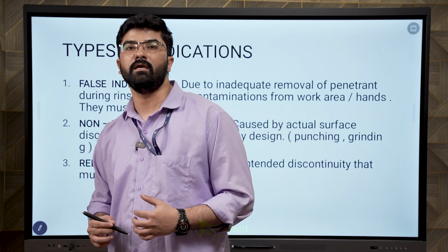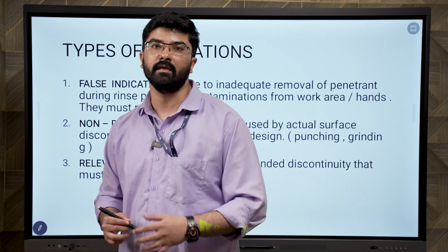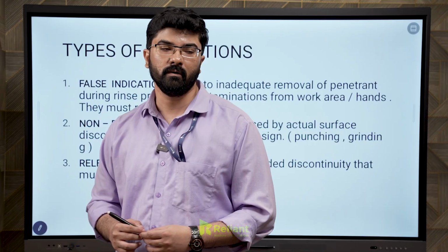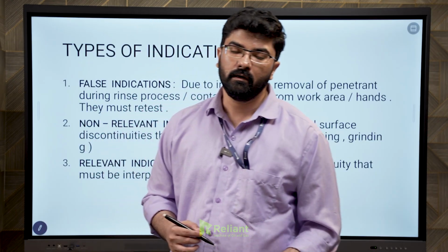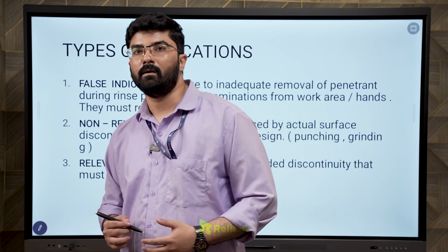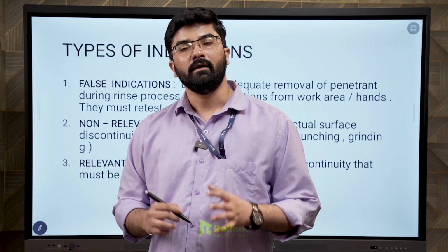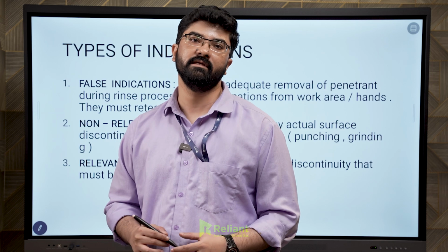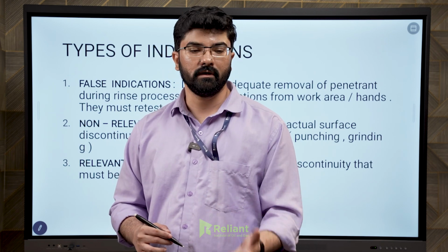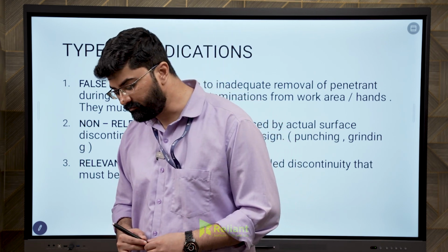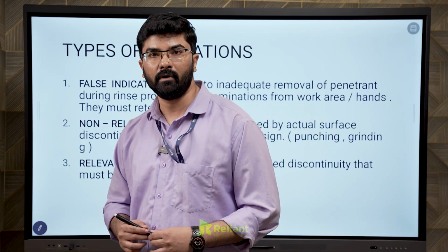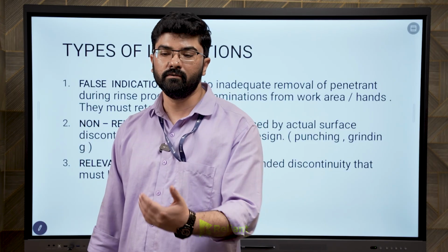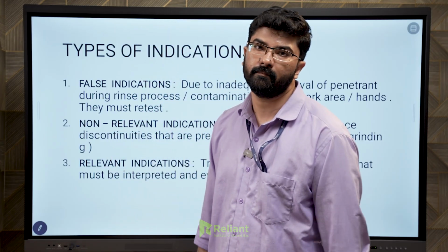When I am at a site, witnessing the penetrant testing, especially wherever it is, a pipeline project, tank storage, or even shipyard, structural, anywhere we conduct penetrant testing, if you find more false indications, we should go for retest. We should not accept the report. Instead we have to assist or advise the technician to conduct a retest on the part.